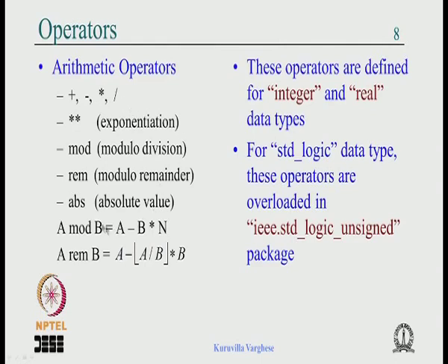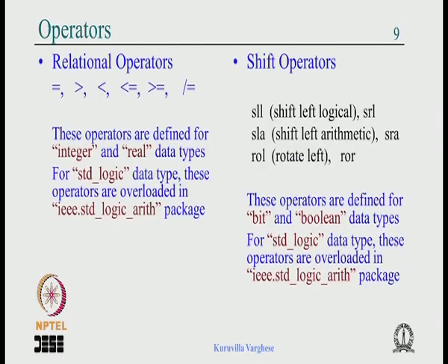Mind you, if you write code with this using standard logic, it might work for simulation, but it may not synthesize and generate a proper circuit for you. You have to keep that in mind. Everything doesn't work; sometimes you have to write your own low level design for some of these to work, or it will give some rudimentary circuit which is not what we want and things like that. So you have to keep that in mind.